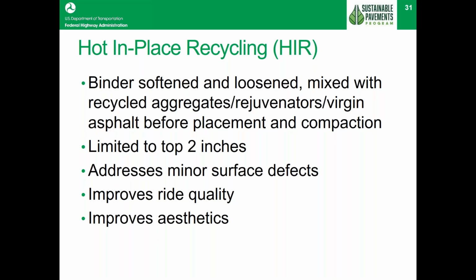It's a little bit expensive to do, but as I said before, where trucking is really a big issue, this can be a very cost-effective element to do. This is one of the kinds of things that I recall doing back when I was an engineer out in Nevada, and it was 50 miles to the nearest asphalt plant. So it made hot in place recycling something that was very practical to do on a lot of these kinds of roadways.